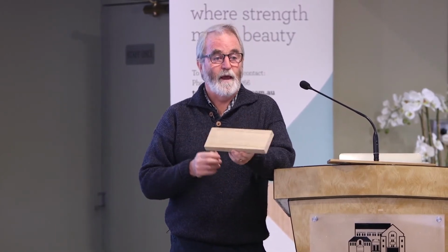Now, for a little job like I'm going to put a bench in here, I'm going to put a bit of strip flooring across this space, it's not going to be critical. But if I've got 4 basketball courts in a row, then I really want to make sure my moisture content is perfect and that the conditions under which I put the timber are going to stay that way for all of its service life.